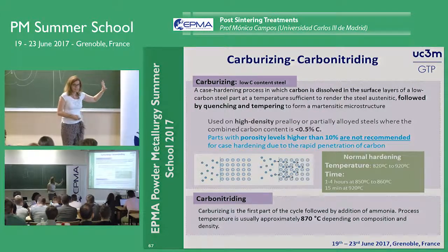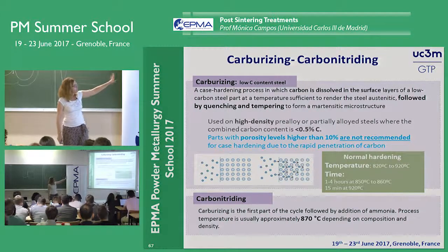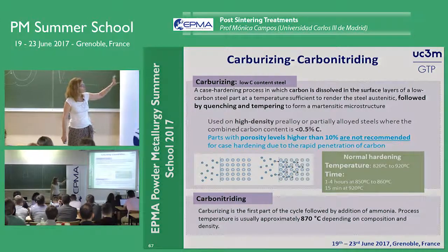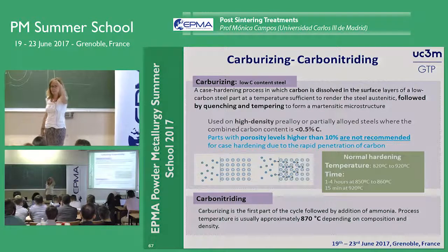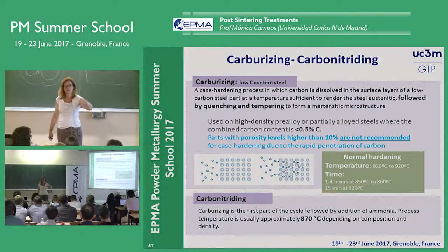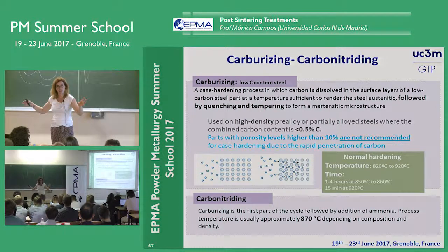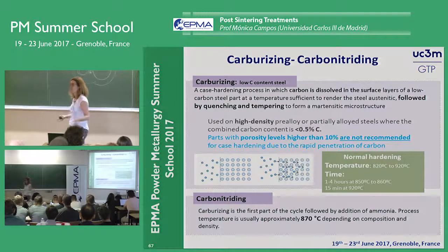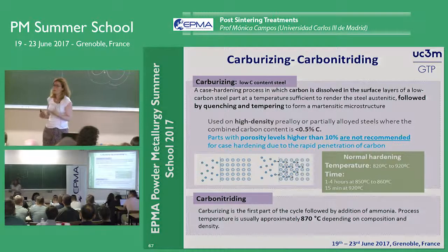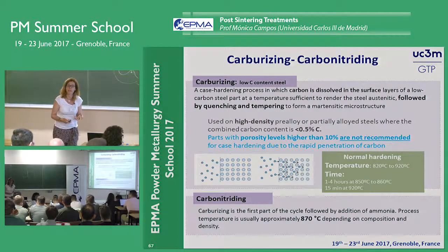In every case of carburizing, you need to quench and temper. Quench and tempering, remember the part that you have seen cooled down in water? Distortion, okay? But carburizing is selected on many occasions because it's very versatile for PM materials.